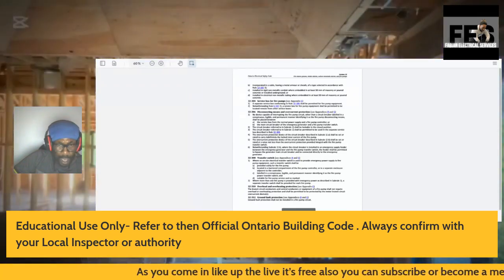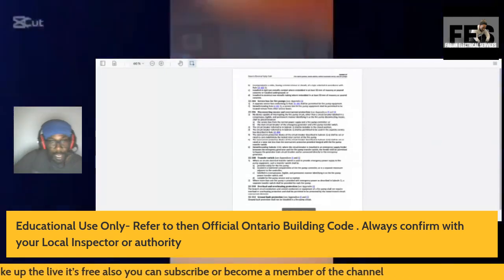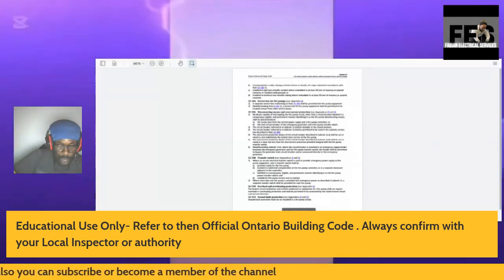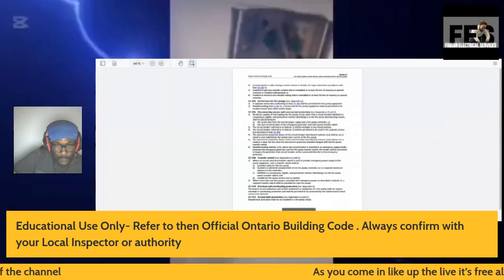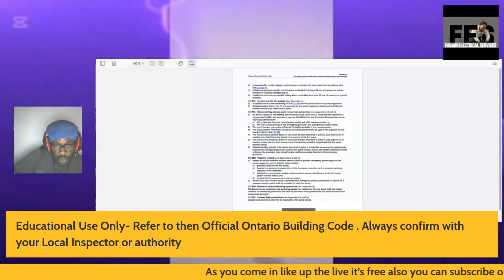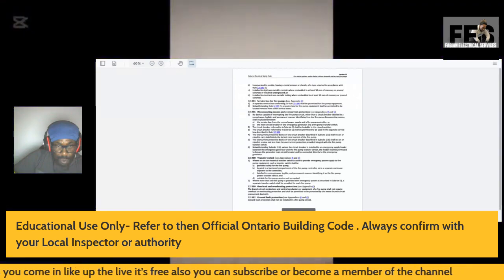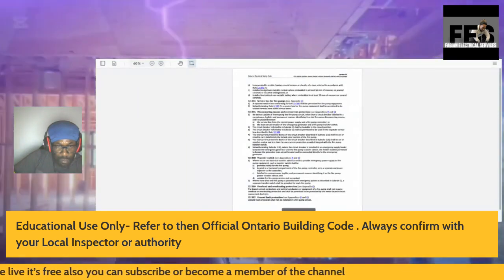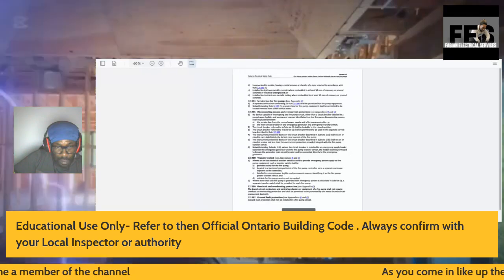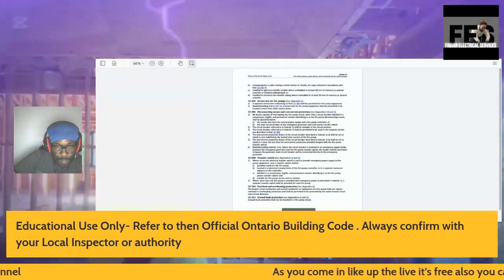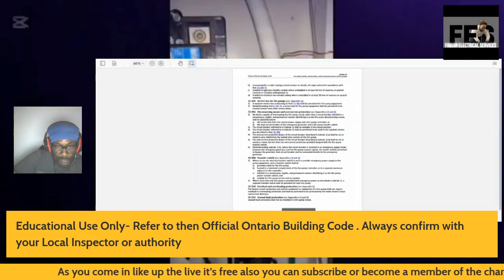It also has the transfer switch, and it tells you to see Appendix B and G. So I would basically refer to Appendix B and G. Where an on-site electrical transfer switch is used to provide emergency power supply to fire pump equipment, such a transfer switch shall be provided solely for the fire pumps, located in a barriered compartment of the fire pump controller or in a separate enclosure adjacent to the controller, labeled in a conspicuous manner.